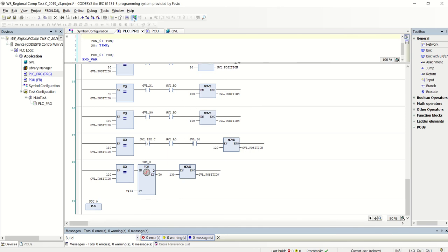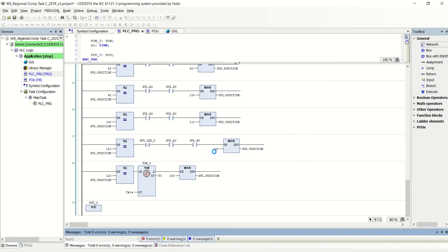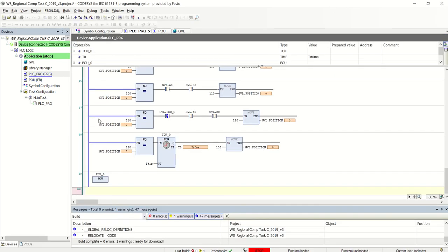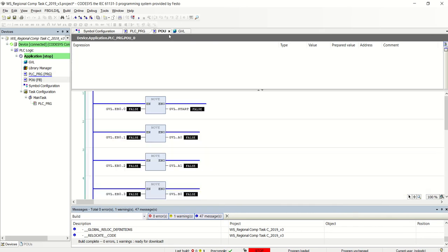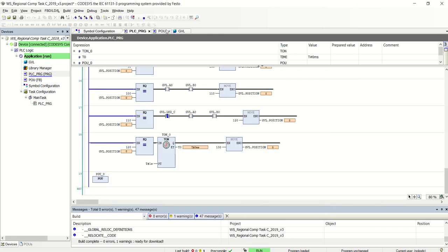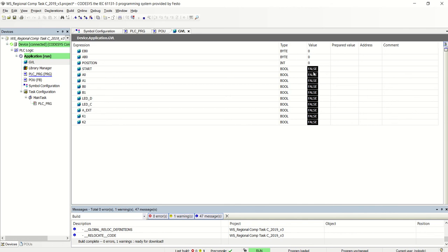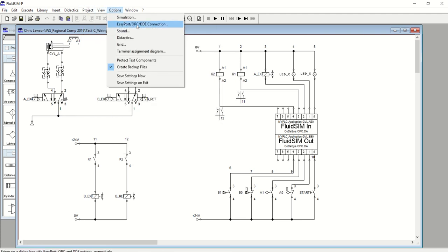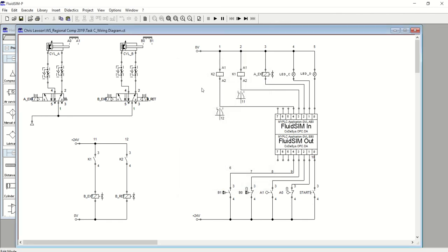I just want to see it simulating. So if we log in, we're logging into a virtual PLC. Again, that's another bit of software that comes with Codesys. Okay. Then what we're going to do is press play on our simulation. You'll see nothing's happening. Everything's false. We go in here and make sure this is set up for OPC communication, looking for the correct bits of the application. Again, I have videos on it, so make sure it's in OPC mode and it's looking for the correct bytes.